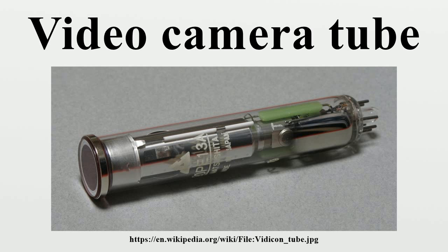The target is constructed of a mosaic of electrically isolated metallic granules separated from a common plate by a thin layer of isolating material, so that the positive charge resulting from the secondary emission is stored in the granules. Finally, an electron beam periodically sweeps across the target, effectively scanning the stored image, discharging each granule, and producing an electronic signal like in the Iconoscope.